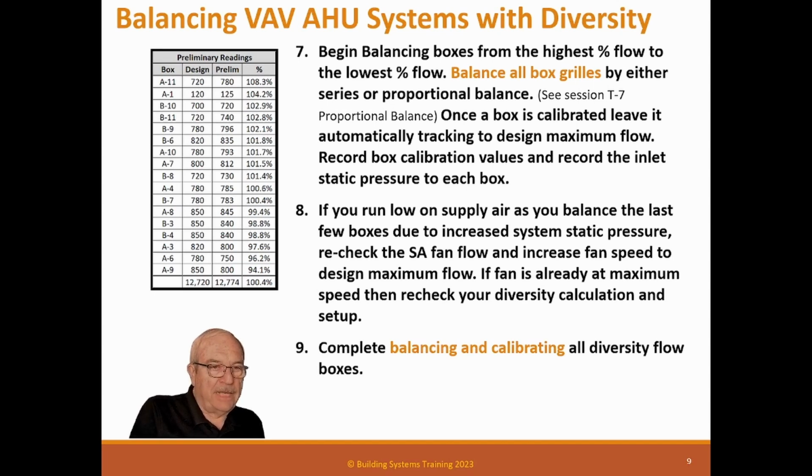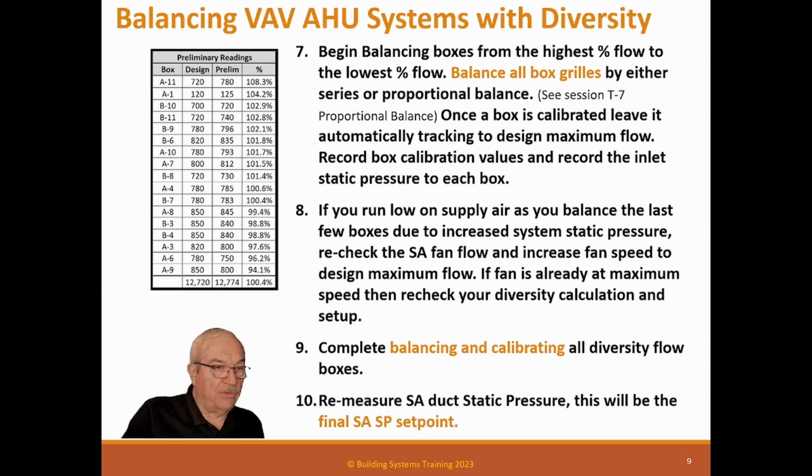Complete balancing and calibrating all diversity flow boxes. So all the boxes that you didn't close, you finish balancing all those. So once you've balanced and calibrated all of those, you remeasure the supply air deck static pressure.